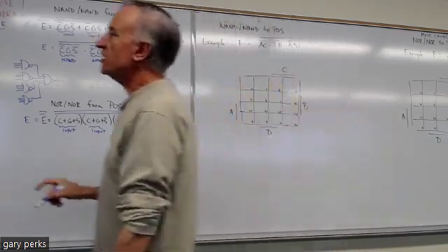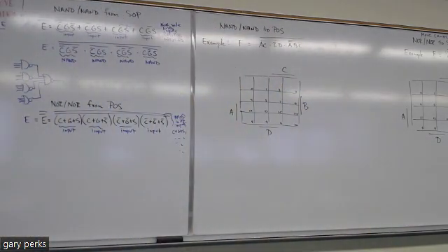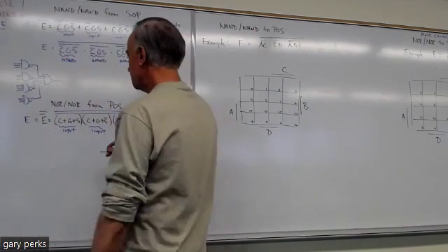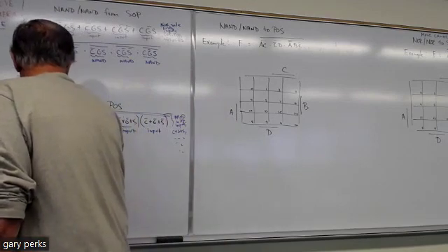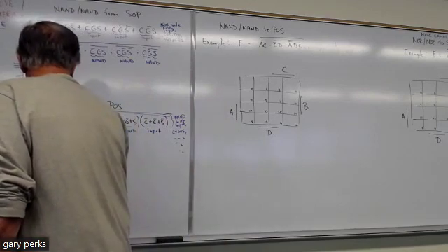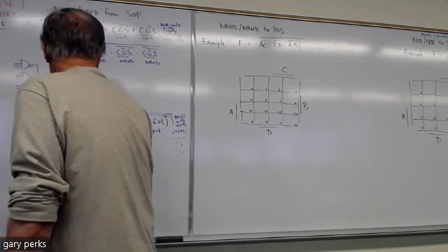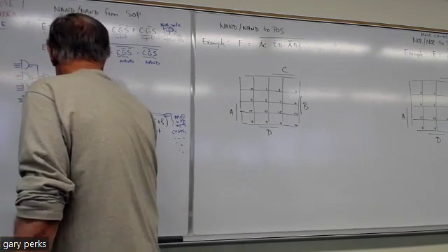And what does De Morgan tell us about an AND gate? Equal to an OR here. Exactly, it's equal to an OR with inverted inputs. So I take each one of these inputs, invert it, and then OR it.